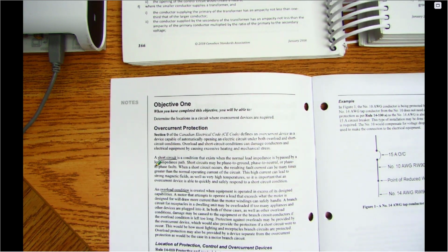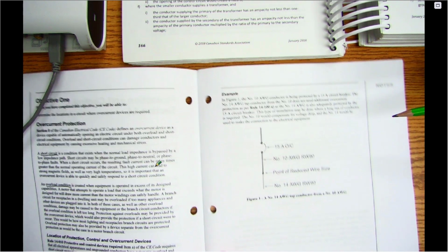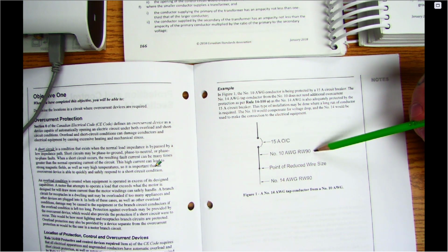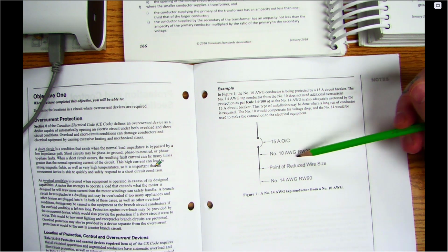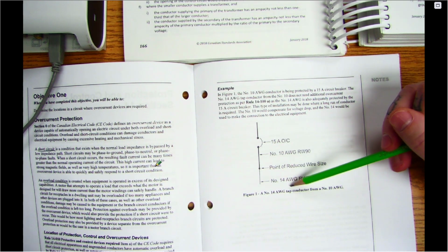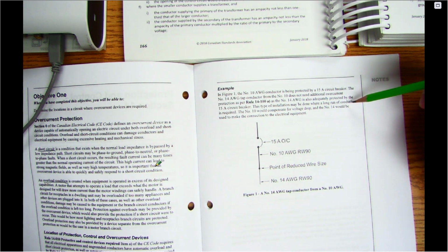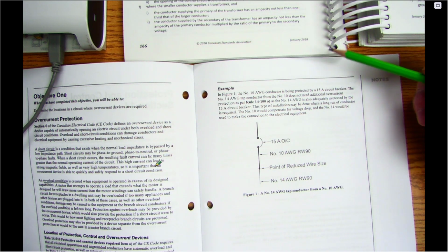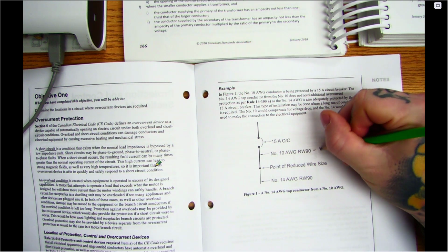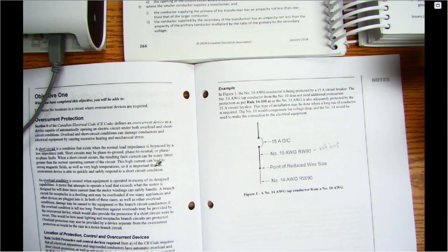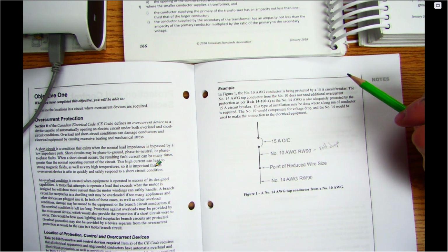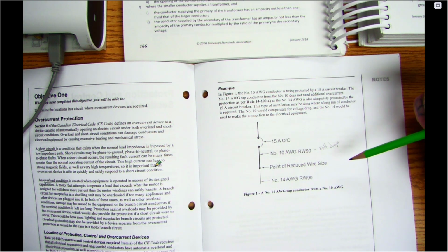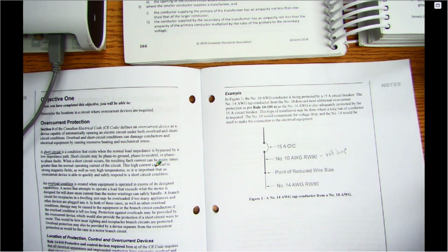So they talk about it here. First one they go through in this example is basically just a reduction potentially due to an increase due to a volt drop scenario. So I have a 15 amp overcurrent, have number 10s, and then I've gone down to 14s. The reason why it's okay is just because the breaker is rated to protect either one of these. And again, this is due to volt drop. So there's an increase of that wire due to volt drop. And this will properly protect the smaller of the two conductors. So this scenario is good. Okay, so that's the first one.